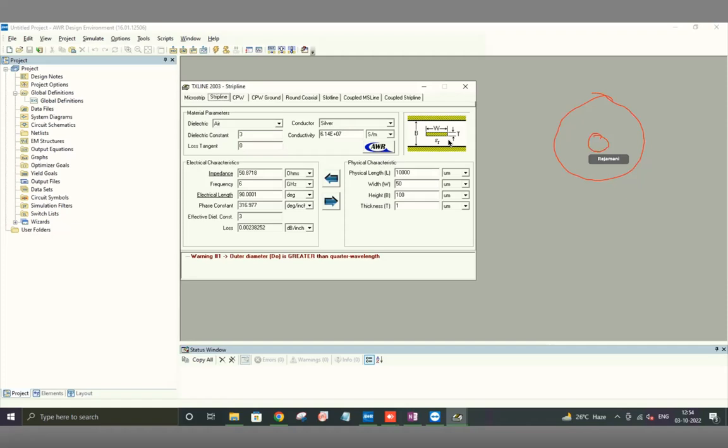So you have your coax, right? I cut it here and I cut it here. And then I sort of stretch it out. Cut it in the middle, the ground plane, stretch it out, put one part on the bottom and one part on the top. And then I change the center part to now look like a rectangle. That's one way of thinking about how you went from a coaxial line to a straight line. Just to understand the similarities between them.